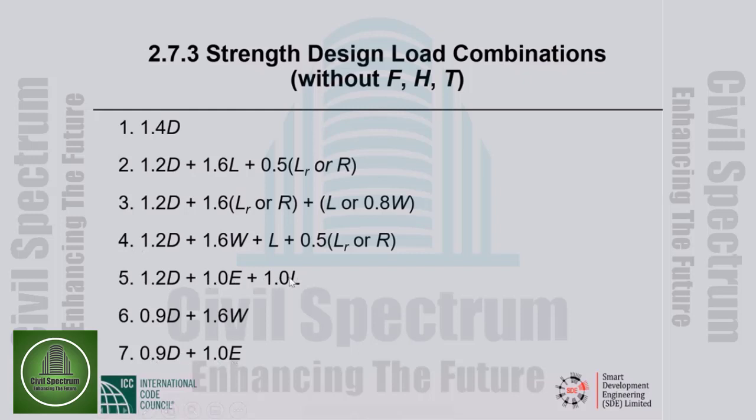This is the additive seismic load combination. Gravity effects add to seismic effects. Gravity causes negative bending moment at the support section of a beam. Earthquake also causes negative bending moment. If we want to figure out the largest negative bending moment, we use the additive seismic load combination.